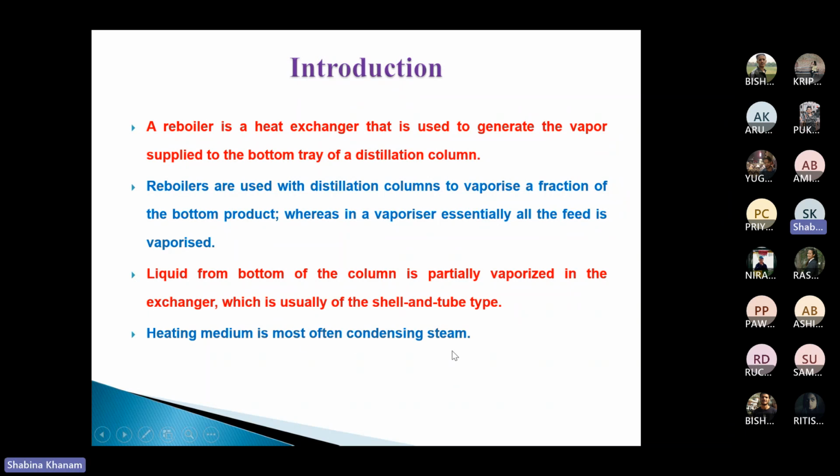It means one fluid is steam, and the second fluid is liquid, which is already at boiling point, because it needs to leave the distillation column and enter the reboiler. In that space, if some heat loss occurs, it may drop by 1 or 2 degrees below its boiling point when reaching the reboiler. Otherwise, it is mostly at boiling point.